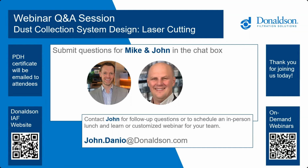So essentially, that's the dust hazard analysis we mentioned previously. That's going to determine if the dust truly is fully oxidized, because to that person's point, that's kind of the key factor here. We can't always guarantee that the dust is going to be fully oxidized. And if the dust is not, that's a contributing factor to an event that could possibly occur.